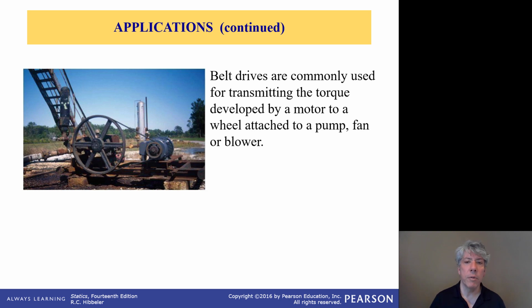Anyway, so how do we deal with a belt like this? Because you might think, well, so far we've learned about pulleys in this class, and when there's no torque on the pulley, well, then the tension on either side of the rope or belt or whatever it is the same. That's true, but when there's torque being applied, because that's really what this motor does, it applies torque through rotation, and then the driven machine requires that torque through rotation, then there is a difference. There has to be a difference in the tension on the two sides of the belt.